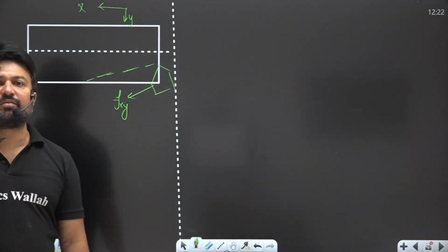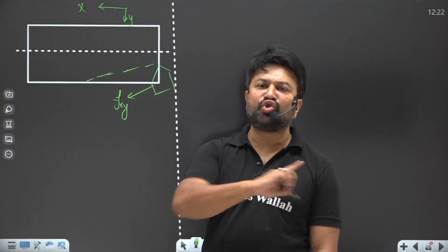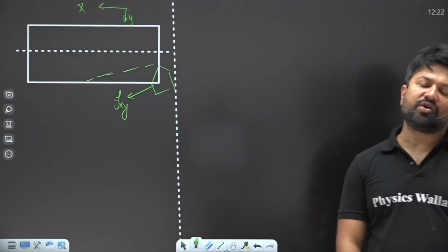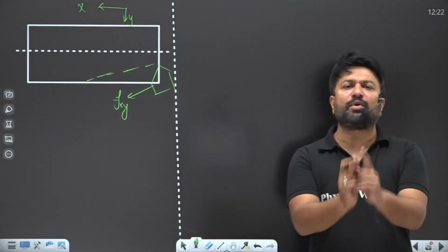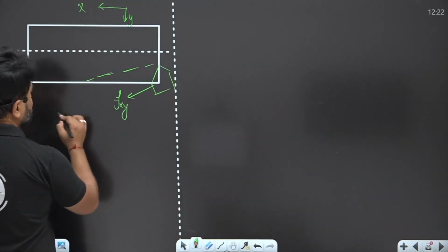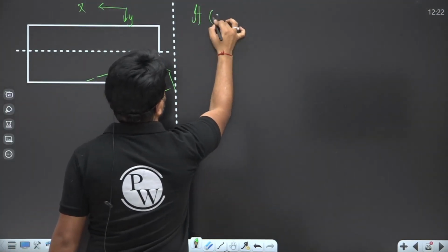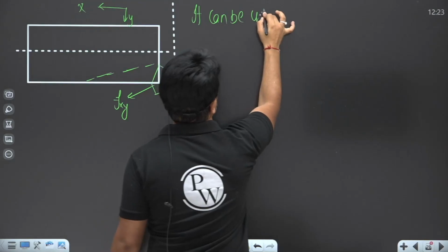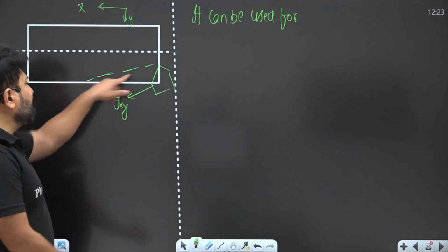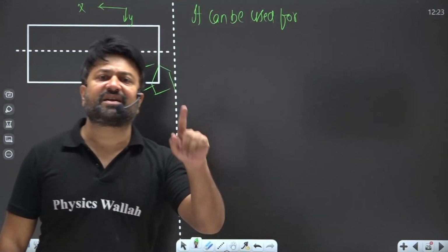So here, limited movement of the compound slide, feed is given by hand and is non-uniform. This is responsible for low productivity and low surface finish. It can be used because manually given feed produces a rough surface.